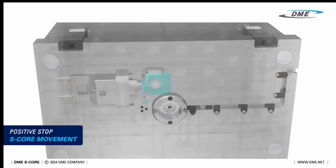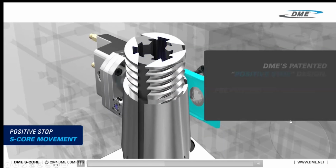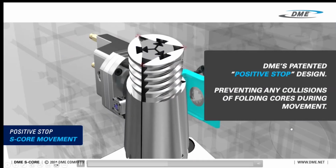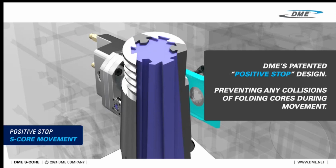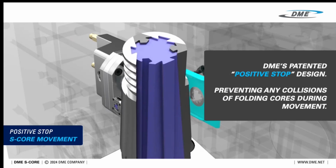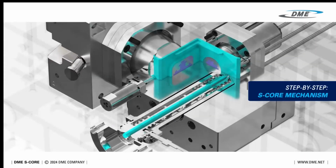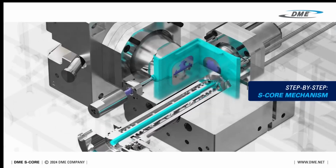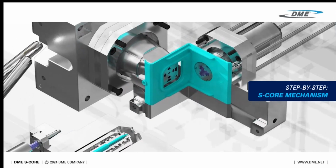Here, we take a closer look at the innovative S-core in action. Powered by DME's new patented positive stop design, this technology eliminates any risk of collision between the folding cores during travel, ensuring smooth, damage-free operation every time. Let's take a look at the mechanisms of all the S-cores in action. Watch as each core operates in sync, working together to release complex undercuts and eject the part efficiently.